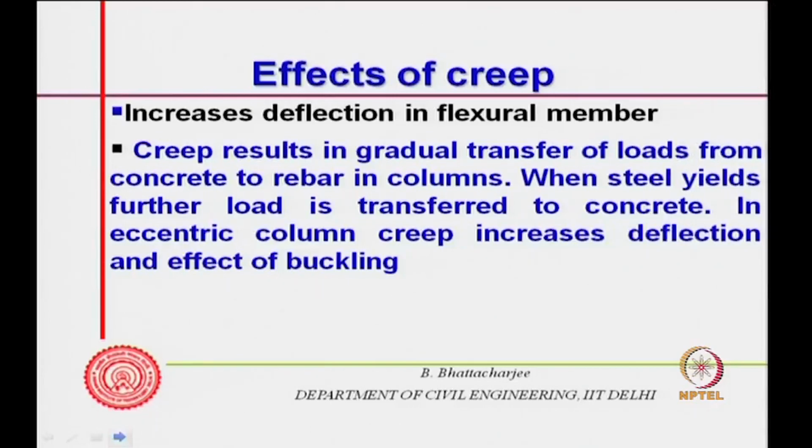Now, you see the creep results in gradual transfer of load from concrete to rebar in columns. Basically, if you have loaded a column, the load is coming onto the column. Now, the bond exists, all right, but the more the stress increases, the more deformation there is, and this will have a tendency to transfer load, because they are under the same deformation. These materials are in parallel.